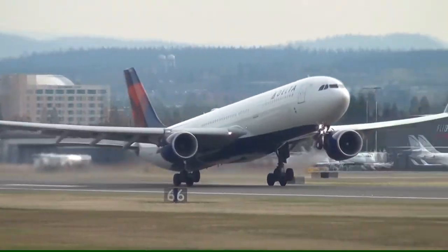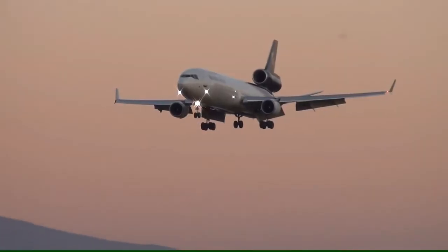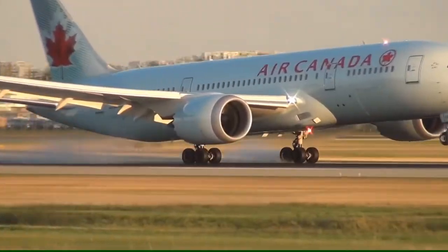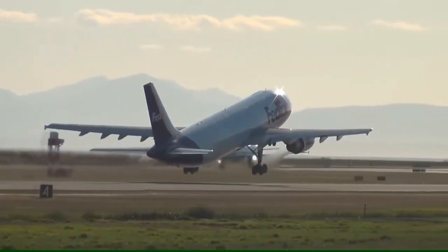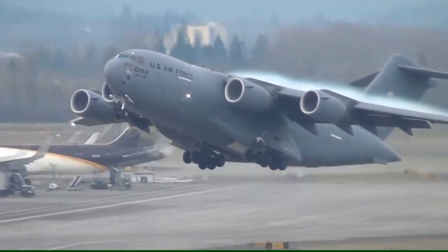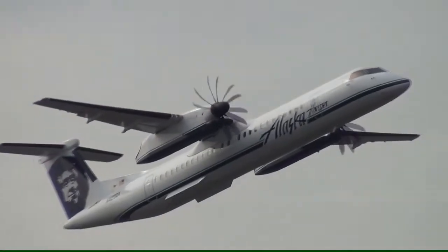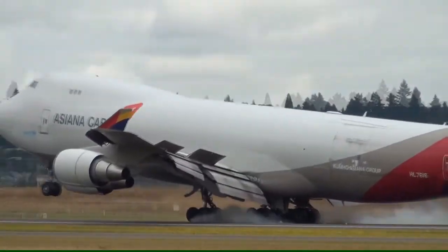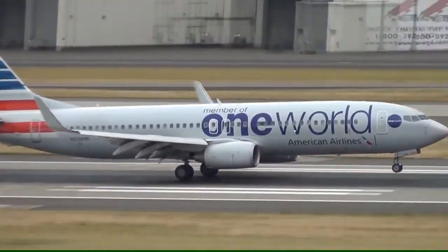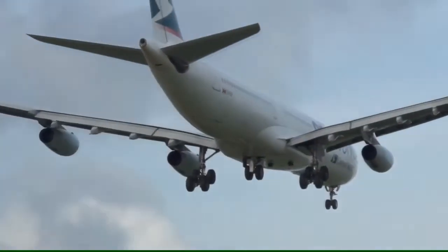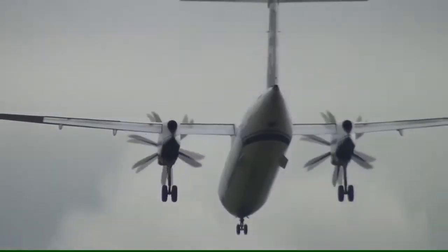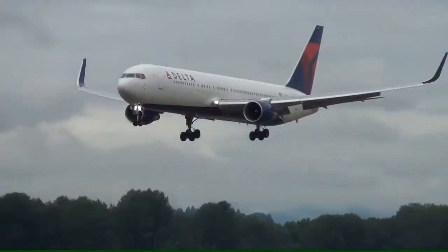Aircraft manufacturer cooperates with both the engine and nacelle manufacturers to ensure the final aircraft meets regulatory requirements as well as its own program objectives. Take the engine oil tank as an example. This is not just the responsibility of the engine manufacturer and is dependent on several aircraft parameters such as operation, flight time, and cockpit indication, as well as engine constraints like oil consumption and pump behavior.